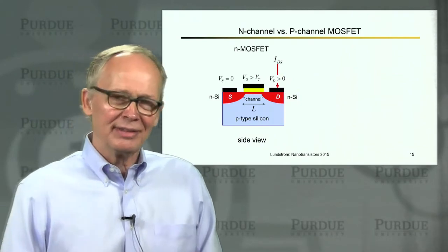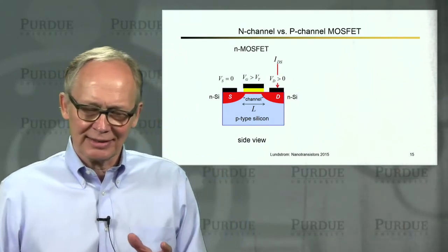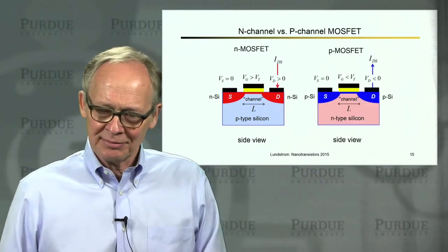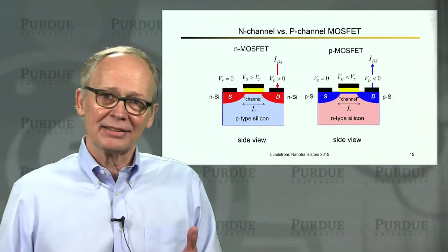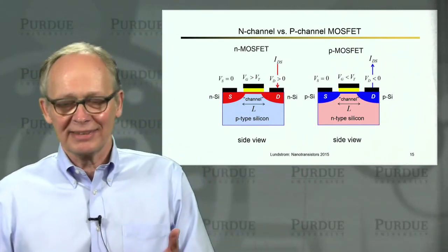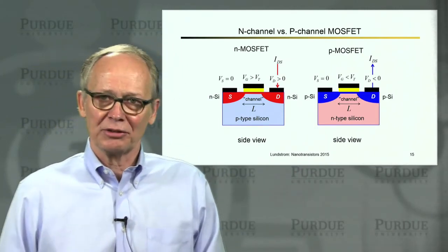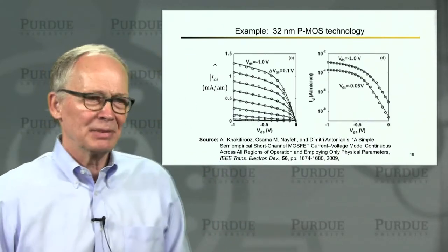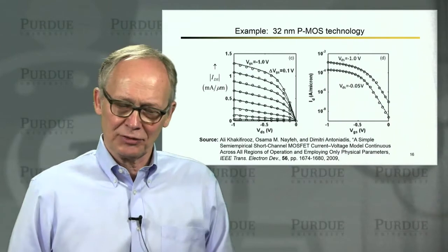And then one more thing. Remember, most of the time, in the interest of time and because the concepts are the same, I'm going to be talking about N-channel transistors. But CMOS technology has just as many P-channel transistors. All of the voltages change sign. All of the currents change direction. The IV characteristics flip around and look like this, but they're basically the same. It's just that everything is flipped.